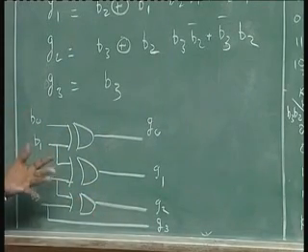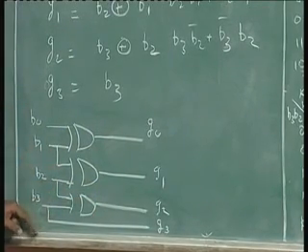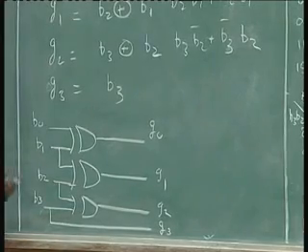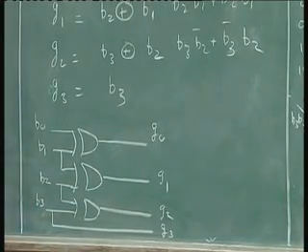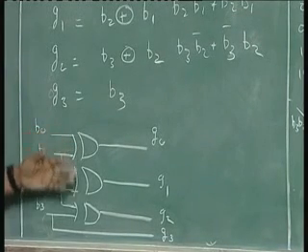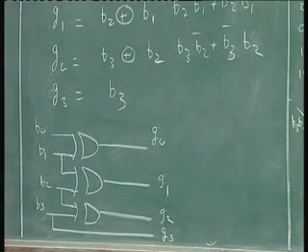The same logic. If it is 5 bits, one more exclusive OR, B3, B4. It goes on. So 7-bit binary code if you have, you can get 7-bit gray code by using 6 exclusive OR gates. It's a very simple, elegant circuit, practically used also. As I said, many times people want to convert digital design, convert the binary code to gray code before doing the processing for all the switching activity and all that I told you, and then get back the binary. So this is a very elegant circuit, commonly used circuit.